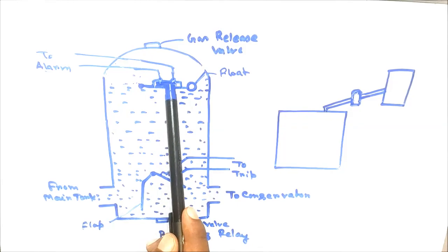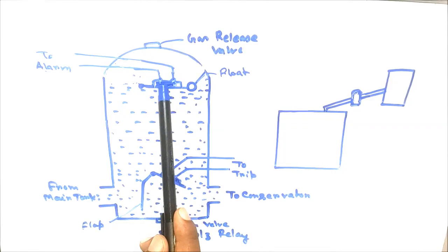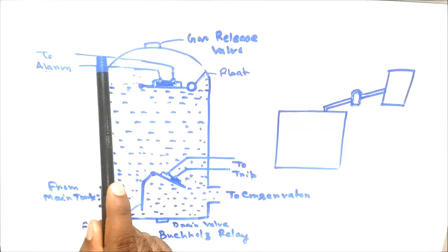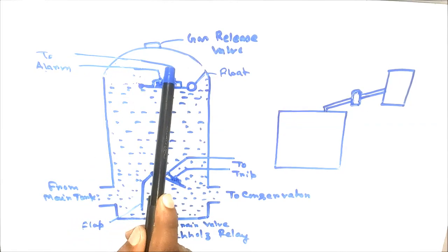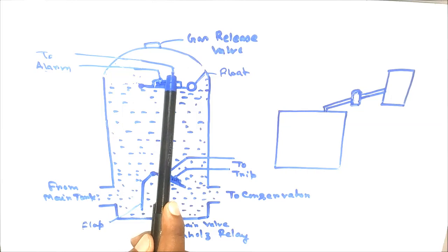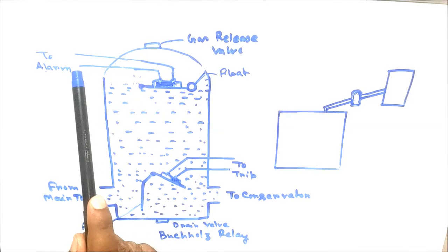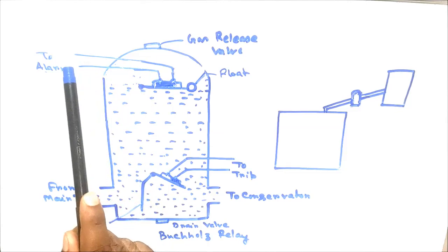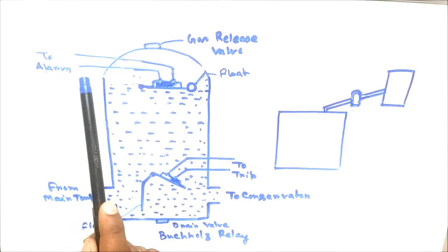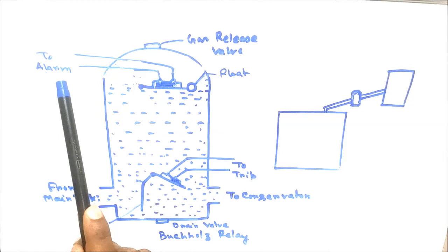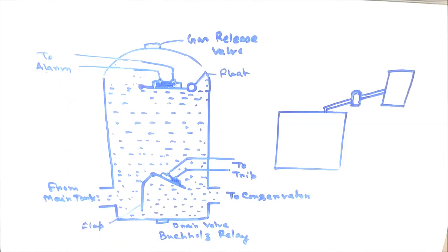Therefore this Mercury switch makes the two electrodes, and the DC connected at one end of the Mercury electrode will flow to the other end of the electrode and the cable connected with this electrode. Therefore the auxiliary relay connected with this cable will actuate, and it will send an alarm signal for an internal fault of the transformer main tank.